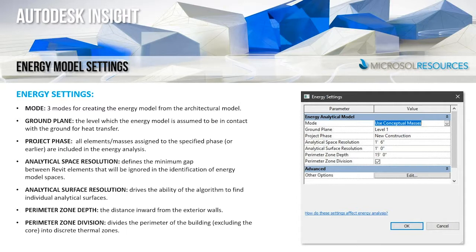Analytical space resolution is the primary parameter that influences the energy model's accuracy and processing time. So this setting right here is what is really going to dictate how long it takes once you've sent it to the cloud. So between the first email that you get saying that, my apologies, that it's been accepted versus the second email that you get saying that it has been processed and is ready for your review. That amount of time is going to be dictated by a number of these settings, but mostly by this analytical